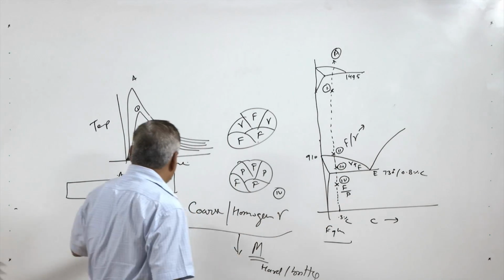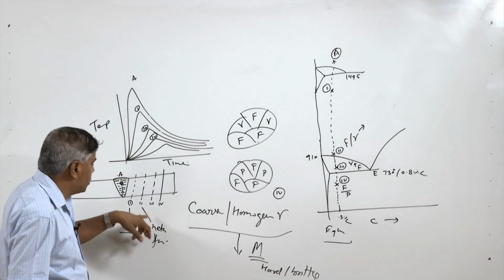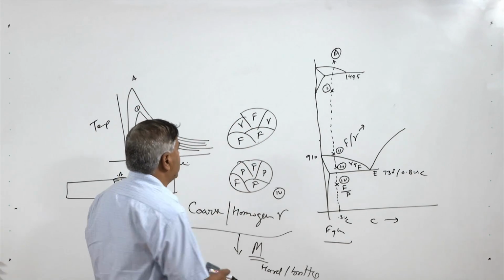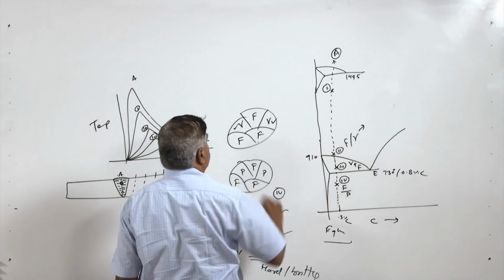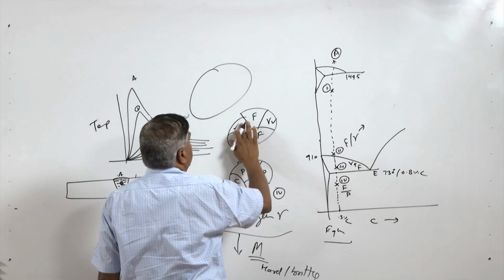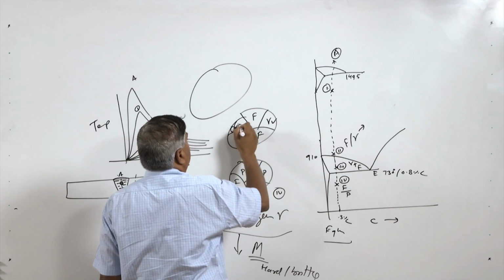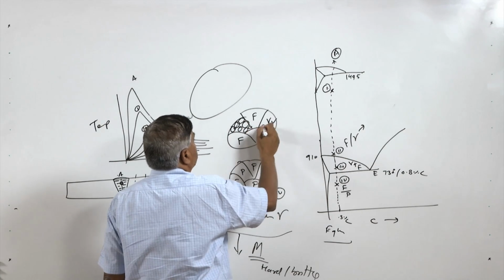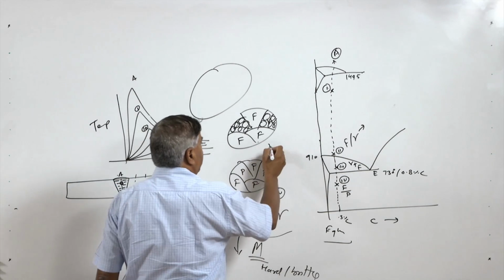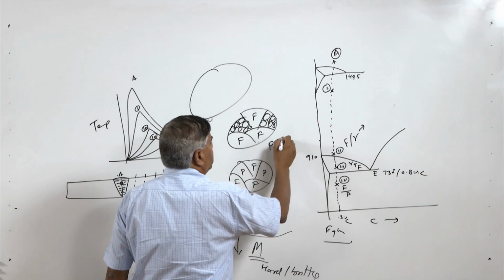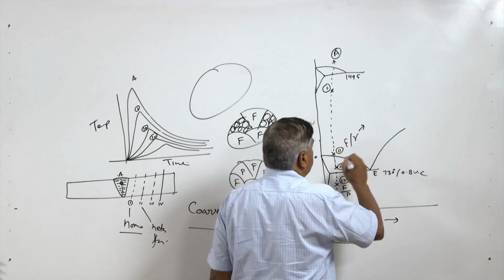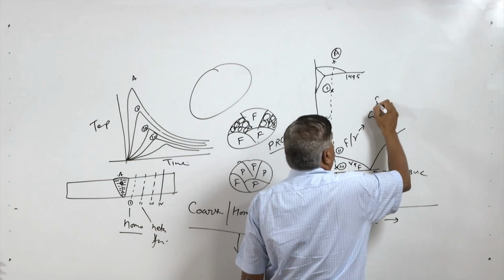During the heating, point 3 will experience both ferrite plus austenite, and subsequent rapid cooling results in the transformation of this gamma into fine pearlite. So the gamma will transform into finer pearlite grains within the austenites. This zone results in the formation of the partially refined grain zone, while zone 2 results in the very fine grained zone.